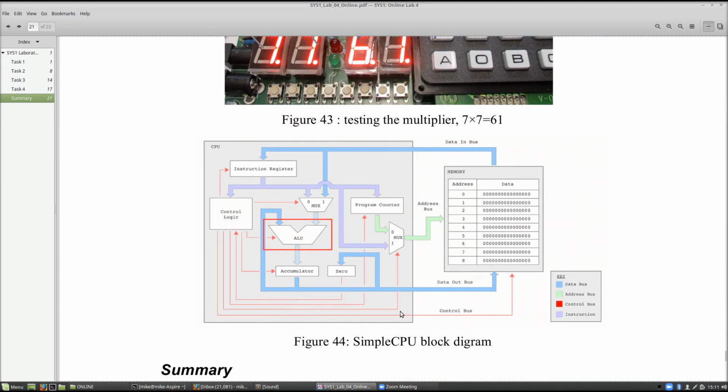As mentioned in the tech support sessions, we have now looked at all the hardware components we need to build our processor. So we looked at the registers this week, the ALU, the multiplexers, control logics, encoders, decoders. So now over the next series of labs and lectures we'll pull those all together, look at the instruction set we'll be designing for the processor, and make our processor and execute some programs.